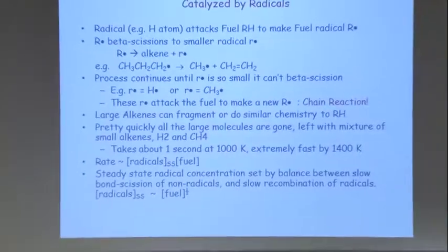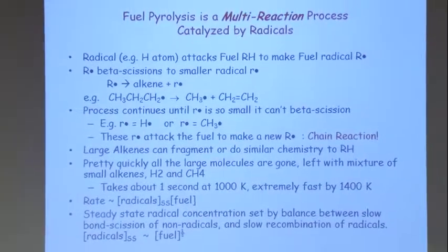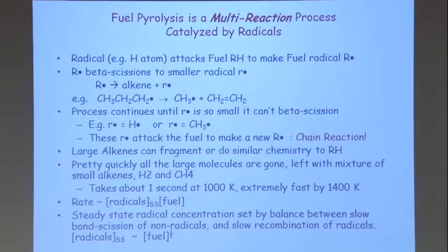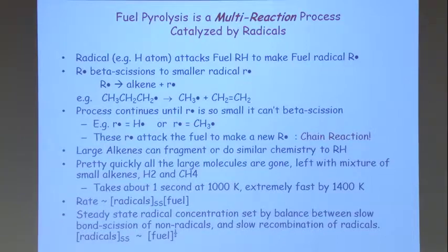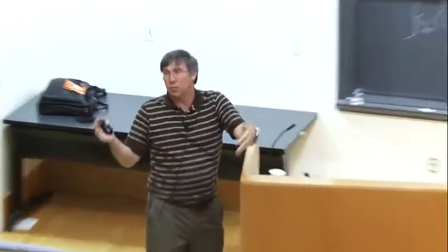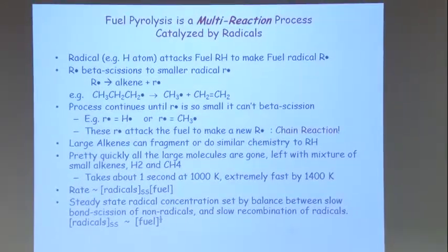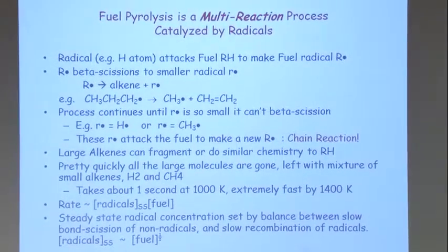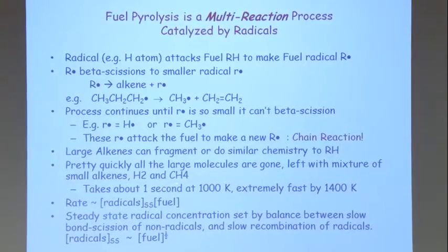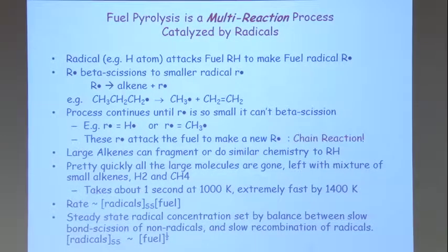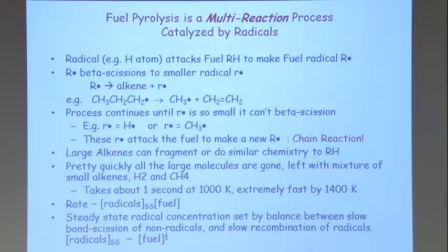All right. Anyway, this is happening also in the flame. In the flame, it's a little bit safer because you don't have a big pipe full of all the fuel. You just squirt a little bit of the fuel in through your fuel injector or something. And so you have a relatively small amount of fuel present, and you expect it to all burn up. So you make the whole thing so you can handle the total heat load from the thing burning up. All right, the rate for this reaction: at 1000 Kelvin, around there, it's about 1 second. That's how they run the commercial units. But if you're running a flame, your temperature is much higher.